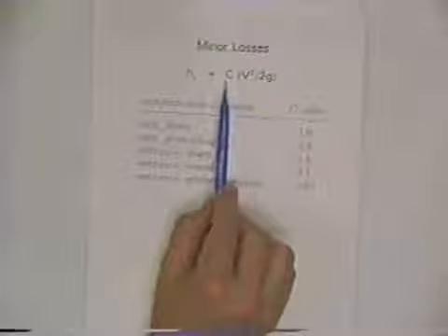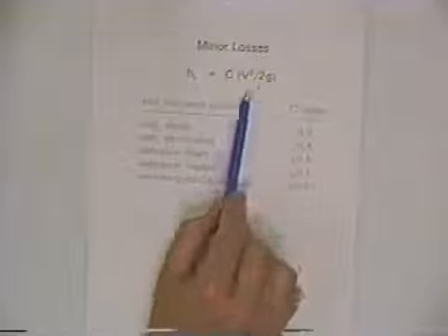And so a common term for these other head losses is minor losses. And in many applications, the minor losses might be quite major, but that's what we call them. They can be expressed in different formats. In your reference manual, the formats are always in the general form of head loss is some minor loss coefficient times a velocity head. And your reference manual uses the term C for the minor loss coefficient.